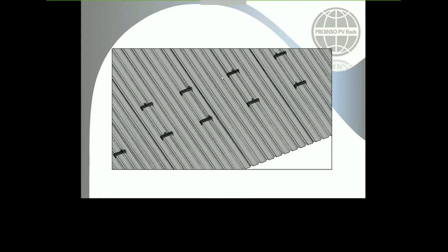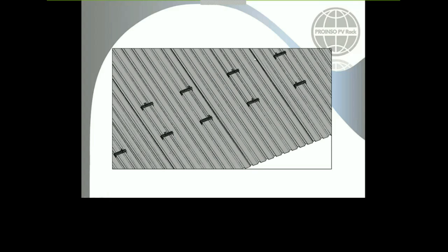It's so flexible as well because you could put the number of points wherever will be required. Imagine that you have an area where the typhoon will come. I think the first thing in a typhoon that is going to go out will be the roof. But if you want to ensure your structure to the roof, imagine that you have to put more points of fixation of these mini rails, okay? This kind of product is really flexible in this way: maybe another one could be installed in here, another one could be installed in here. So you could reinforce your structure in the way you want, okay?